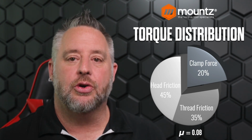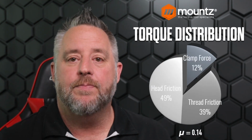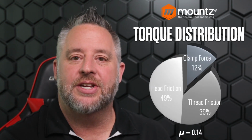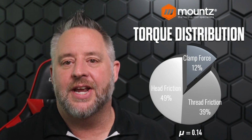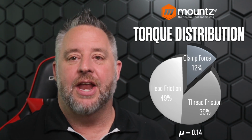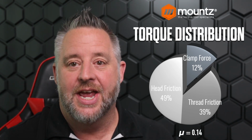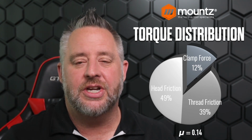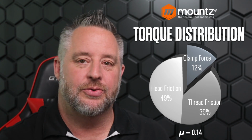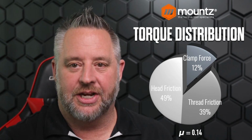Now, if we increase this coefficient of friction to 0.14, you can see that our head friction has increased to 49%, and our thread friction has increased to 39%, and only 12% is going towards our clamp force. So as we increase the coefficient of friction, we are in some cases reducing the clamp force for that particular fastener.